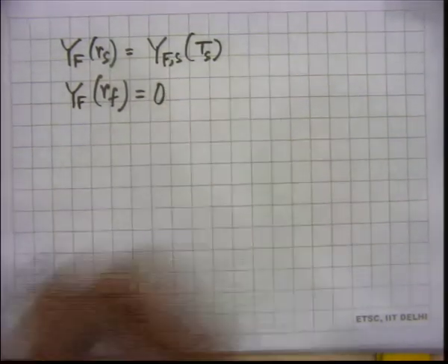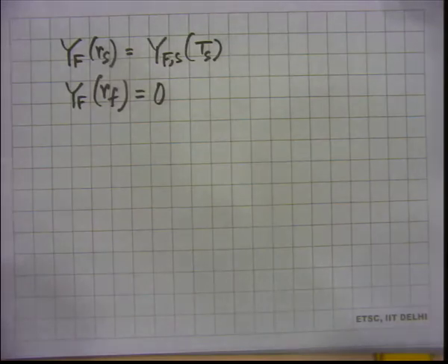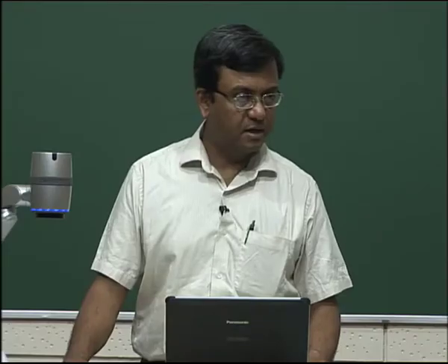This is 0 because we are taking the flame sheet approximation. There is no fuel which will exist at the flame. At the flame, it's all products. Okay, fuel and oxidizer come, they react vigorously, and they give you all products. So what happens at the liquid vapor interface at the droplet surface?